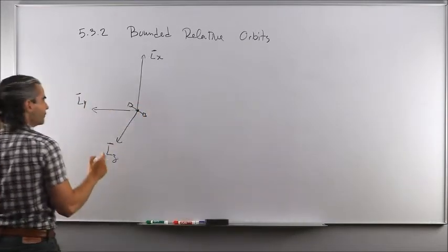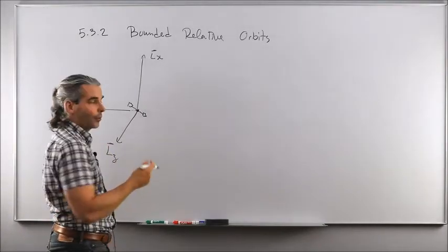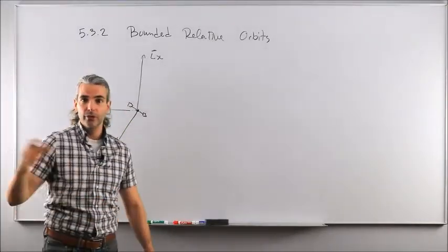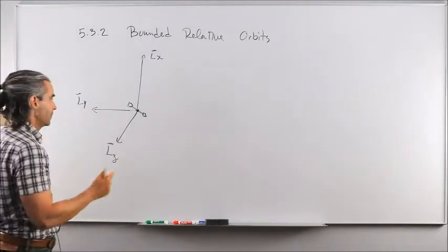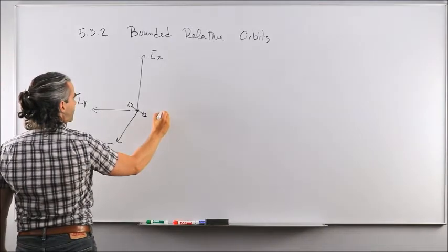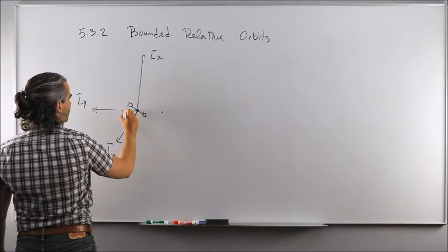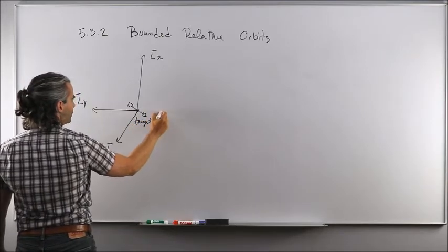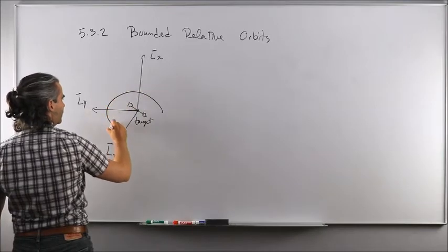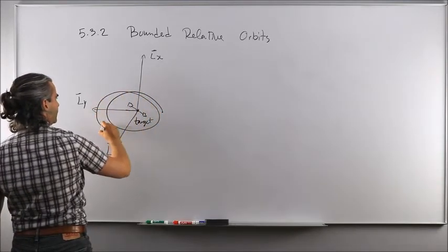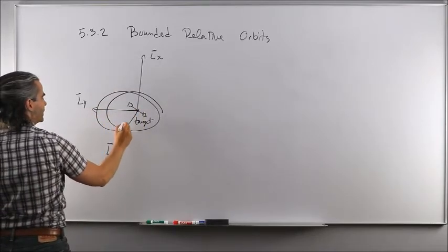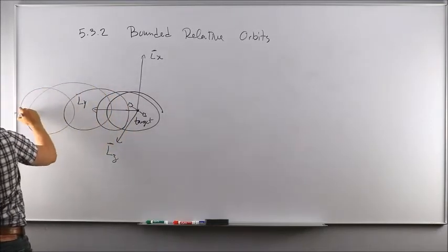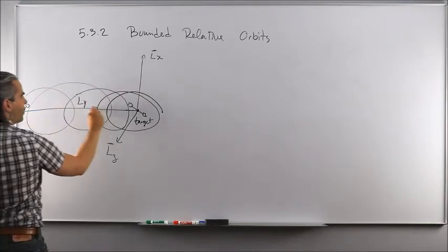and like this. If you don't cancel the linear drift term that was part of the y equation, remember that is the term that was multiplying time, and again because time goes from 0 to infinity, you would get y to just explode as time goes by. So you drop your chaser spacecraft here, say behind the target spacecraft, it doesn't matter. But what you would see is that the relative motion would start, and it would look something like that in LVLH. But then as time goes by, you would see the y component, or the separation between both spacecraft in this direction, to increase and increase and increase. So you see how the chaser is now far away from the target spacecraft.